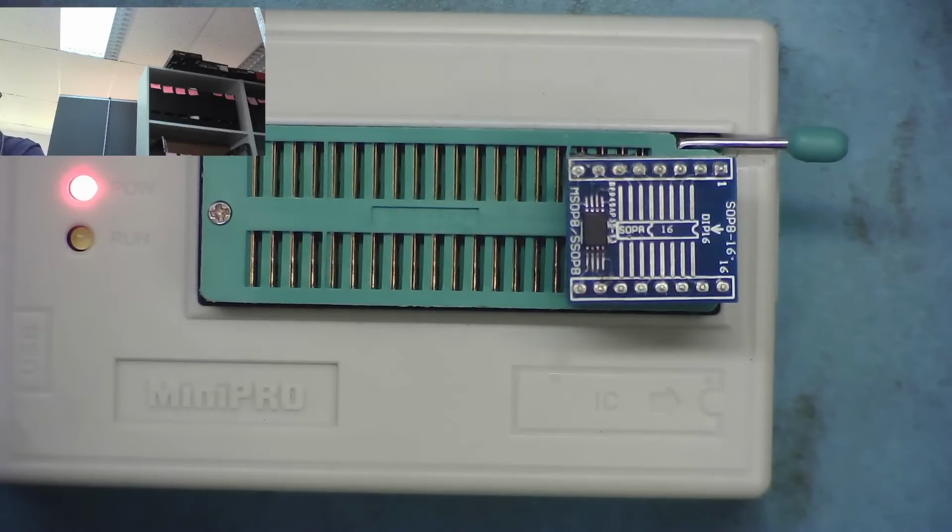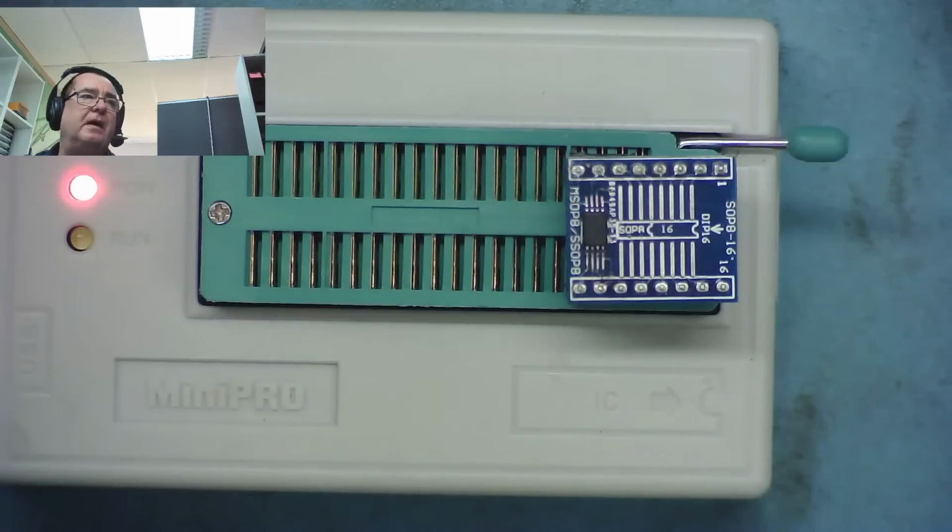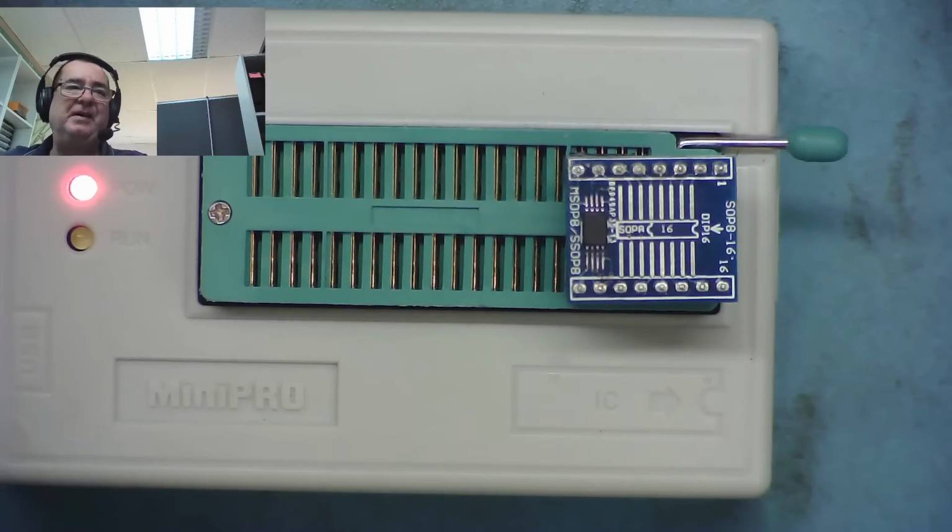So anyway, I asked on the BadCaps forum about it, and one of the guys sent me a private message, and he said, actually, Rich, that problem you've got there is typical, it's classic of a corrupted EDID EPROM. Oh, and by the way, nice video, keep it up. Cheers, man. So anyway, he sent me a file. He said, this is the actual file for the EPROM, have a look at yours and see if it matches. And I said, okay, yeah, cheers, thanks for that.